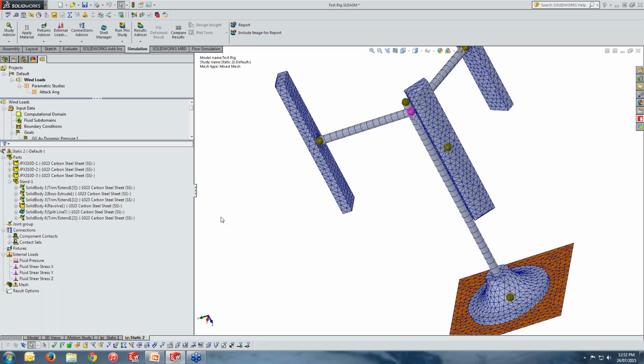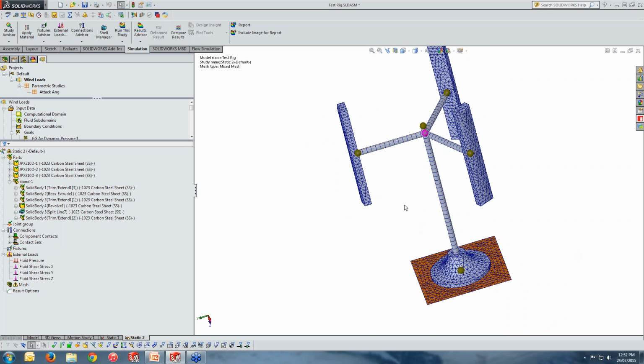That is something very important. If you don't, then the bonded contact between these two types of elements is either not established, or you might create a hinge connection that can simply rotate against the beam element. That is something that needs to be done in order to complete the process.